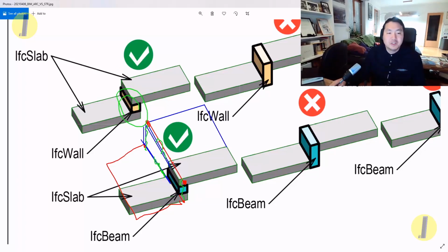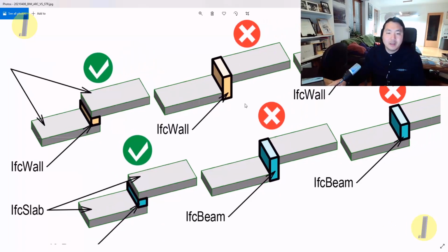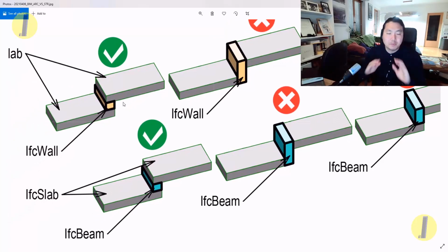So both solutions are correct, but when somebody models this downstand beam or upstand beam with slab like this, it is absolutely not correct. Structurally, analytically, and also in reinforcement detailing, these are not correct. And we should always model as constructed, as built. How we construct in reality makes more sense.